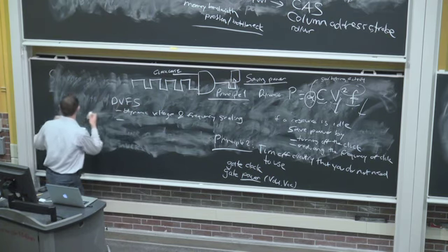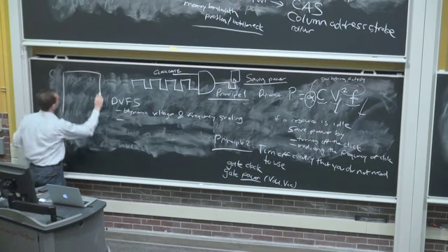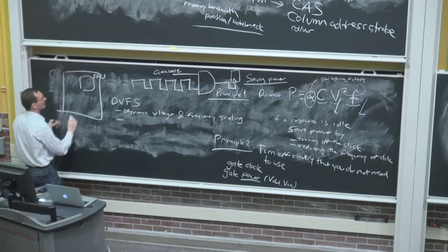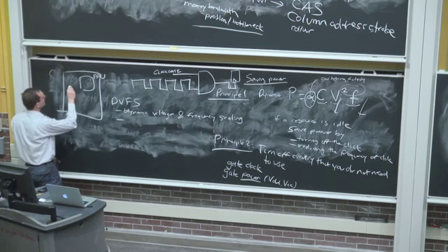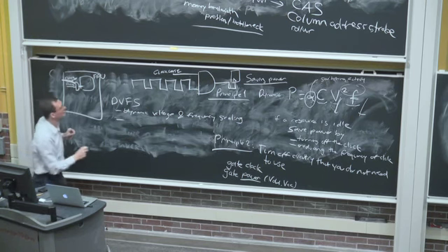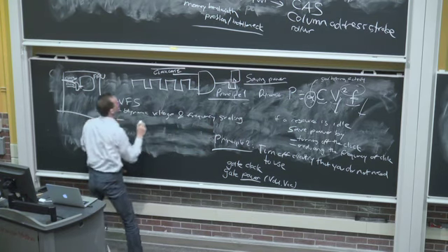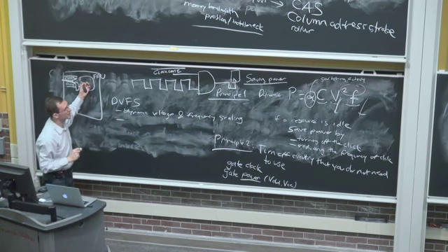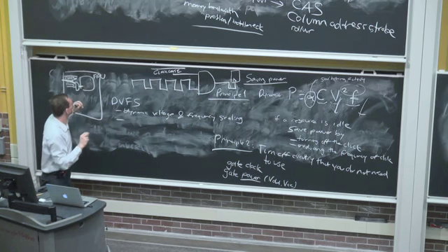So you could think of dividing a chip like a floating point unit. If you're not using the floating point unit, you have the clock signal here, and you have the AND gate, and you have the clock gate signal controlled by some logic. If you're not using the floating point unit, you set the clock gate signal. I guess let's do this bar, huh? Okay? That way you don't consume dynamic power. I'll get to you soon.